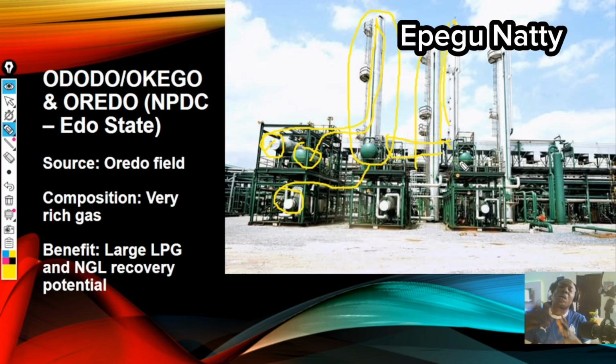So from the air cooler, heat exchanging takes place with atmospheric air, and then it goes down to a reflux drum. The reflux drum sends it back to the top of the tower, as you can see the line going up here to the top of the tower. So, the same thing, it stabilizes the column and all the rest.